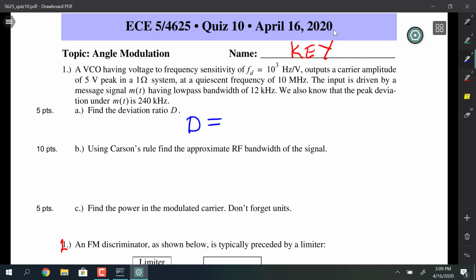It's the ratio of 2 numbers. Yeah. Well, it's not FM though; it's W. So both of you had things that were close. So it's going to be delta F over W, where W is the bandwidth of the message.